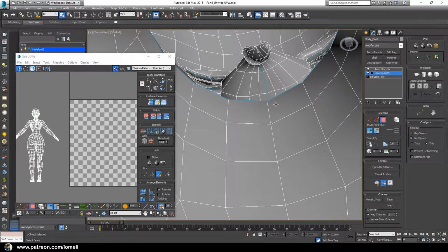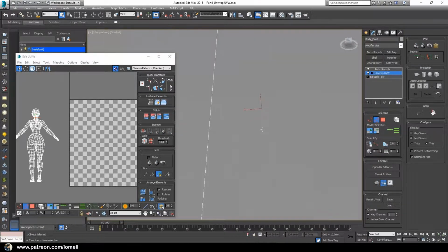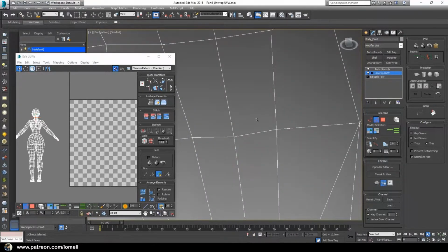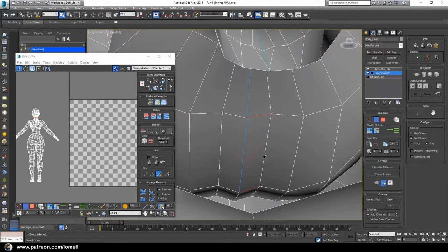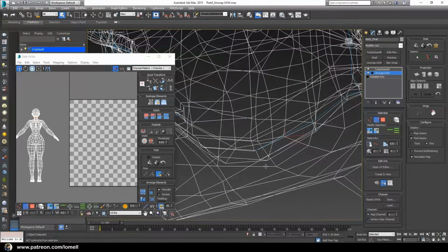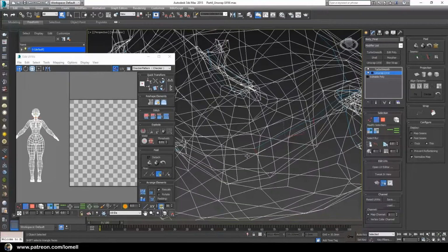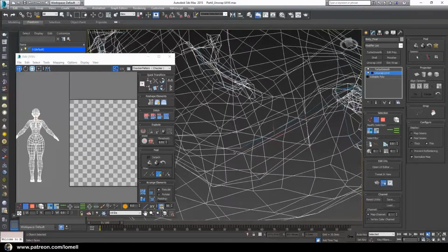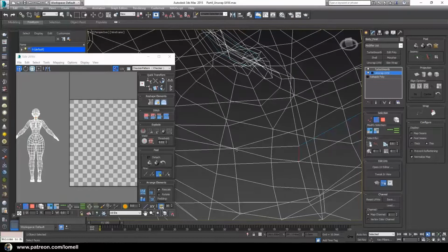Okay, right click to neutralize the mouse and select some edges so that the camera will focus only on this area when we navigate the viewport. Okay, and press F3, Shift Z, press F3, press F3. Okay, and gradually zoom in to that part and establish